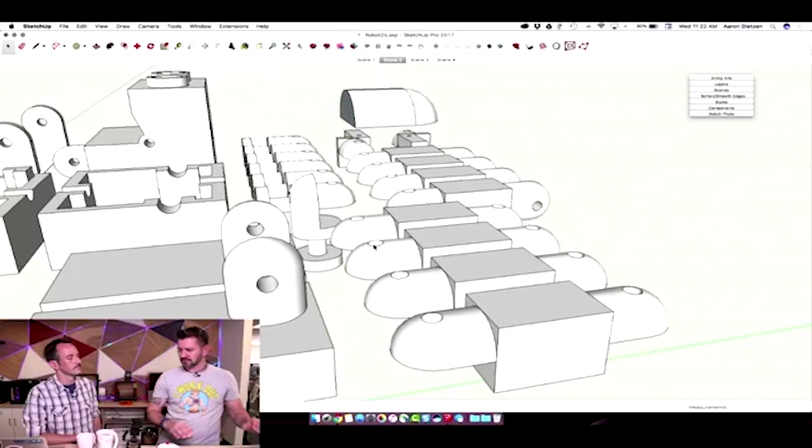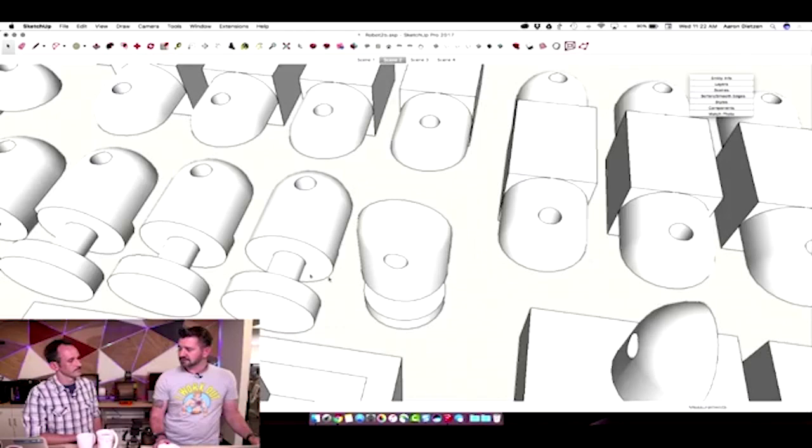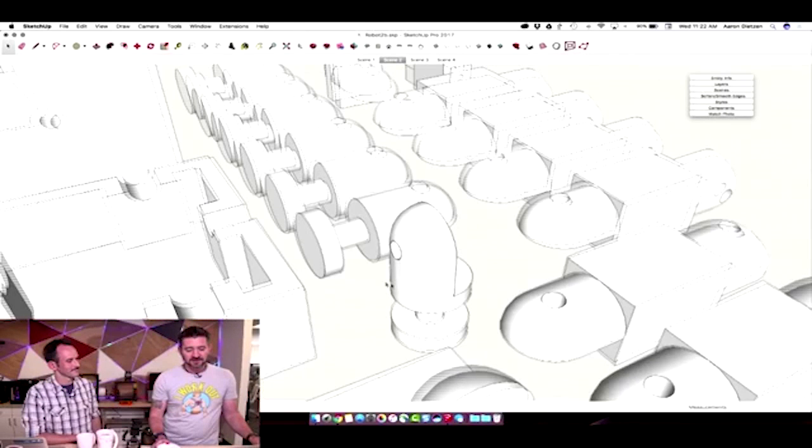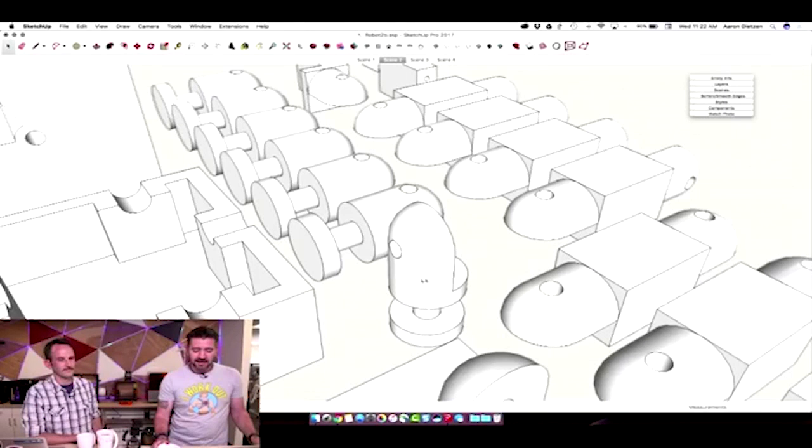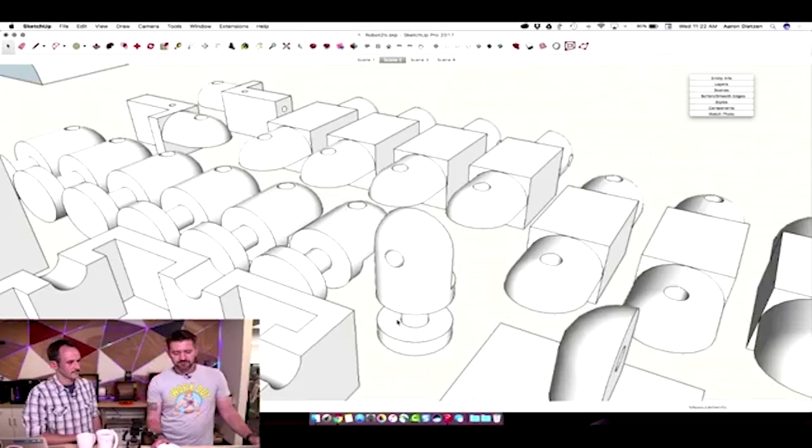So hopping back over to these pieces, like I said, I found out I could not print them laying down because it did not respect the circle geometry very well when I printed. So I tried printing them standing up. They actually came out looking real nice. I had some support material in here I had to break out, but I ran into a new problem.